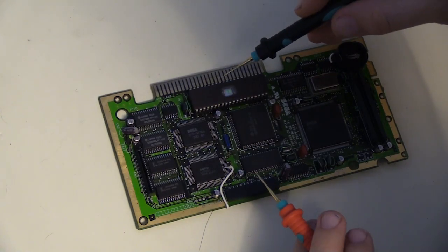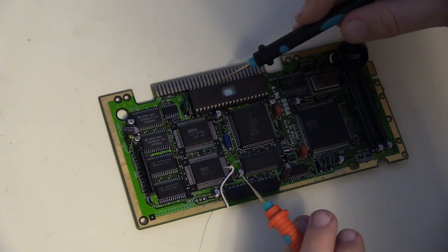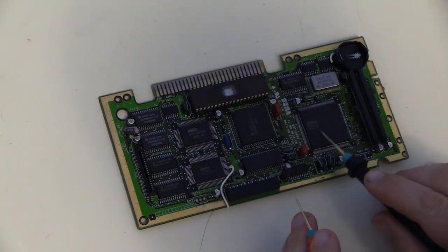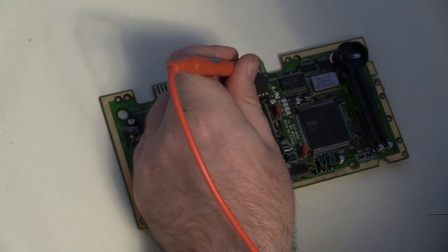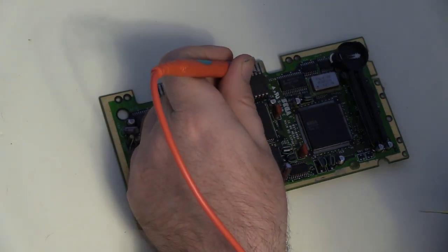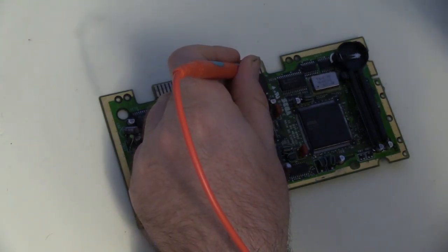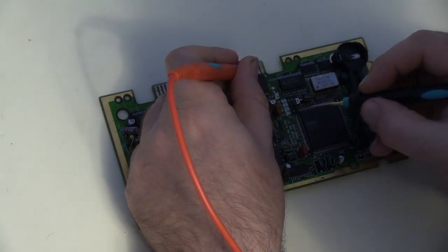So what's happening is that these address lines on the EPROM that the Genesis CPU sets on these pins to read addresses are also shared with the Sega CD processing engine. So if I put my continuity tester here on address line 0, from looking at the schematics, it says that the first address line on the Sega CD processing engine is on pin 171.